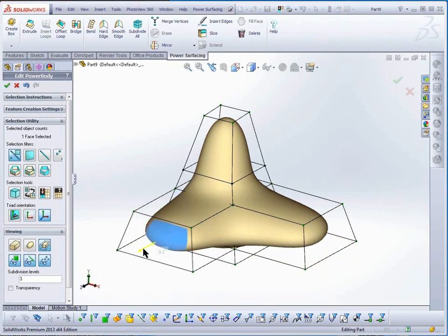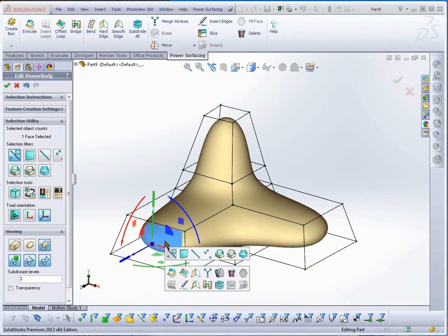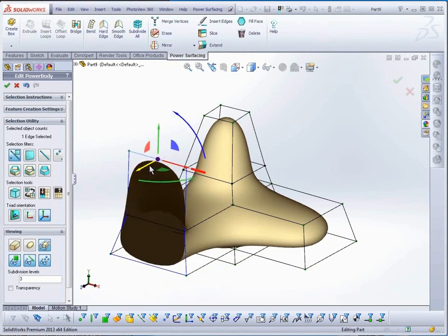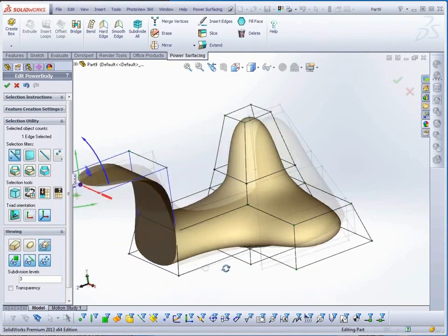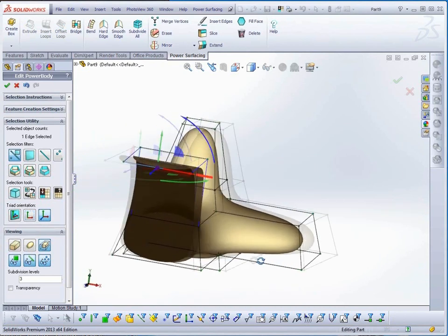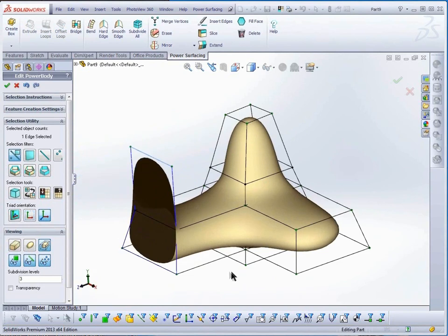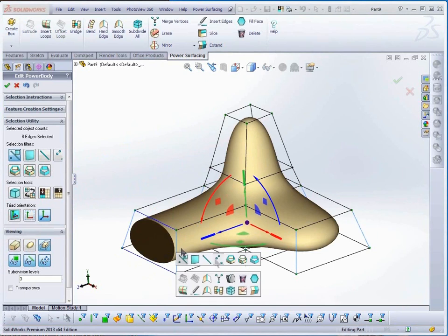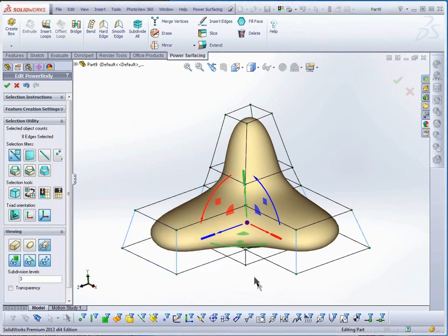The quick extrude also works on open edges, so if you are used to modeling with surfaces rather than volumes, you will probably find it quite useful. I'll delete a face to give me some open edges. Then select one of them and extend it by holding the A key down as I use the triad to move it. I'll do a few undos, and then cap it back up with a fill face from the right-click menu or from the toolbar.